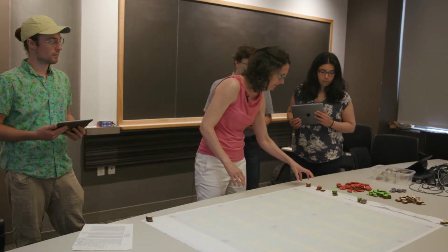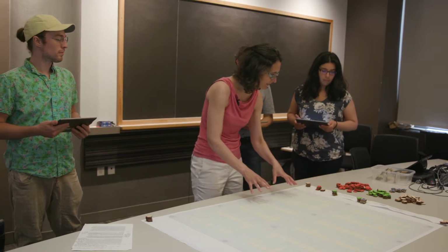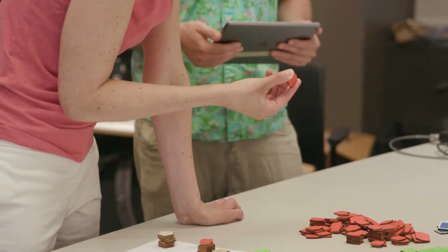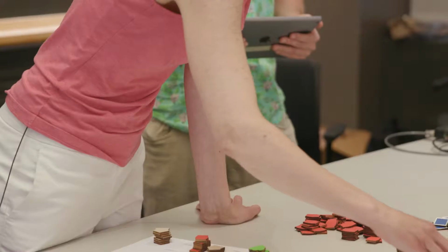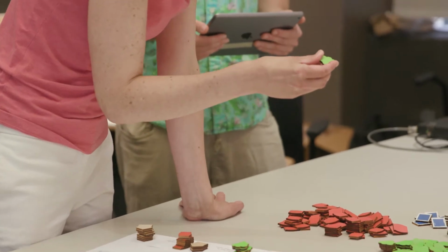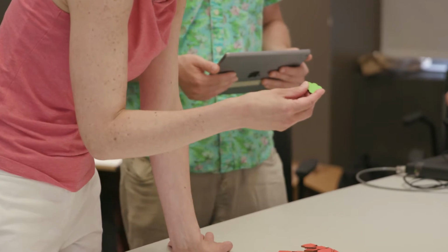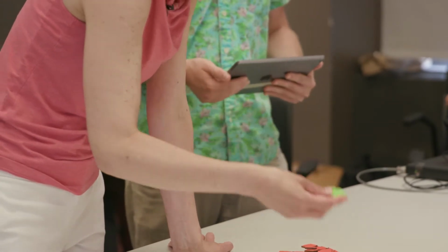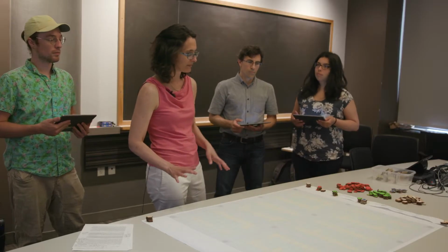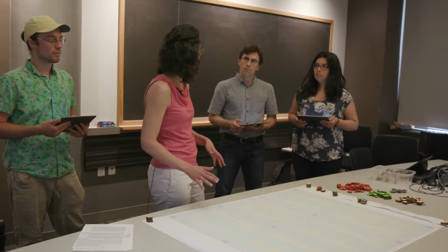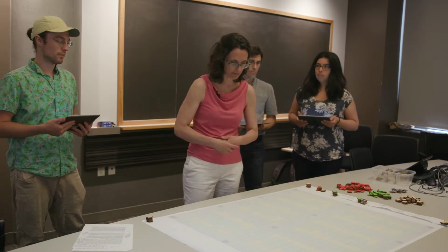And here what we have is different kinds of tiles that represent different kinds of green infrastructure and where they can be placed. So you've got rain barrels and roof gardens that can be placed around buildings. Bioswales can be placed anywhere where it's green, so wherever there is grass. Bioswales can also be placed in areas that are hashed, where there's some kind of pavement, as well as permeable pavers. And each one of them, remember, has a different cost associated with it for implementation, installation, and maintenance.